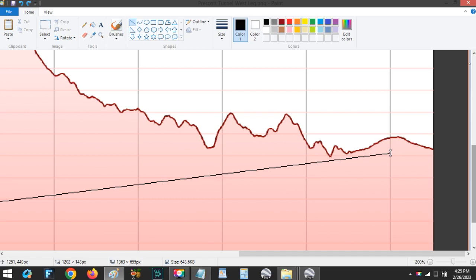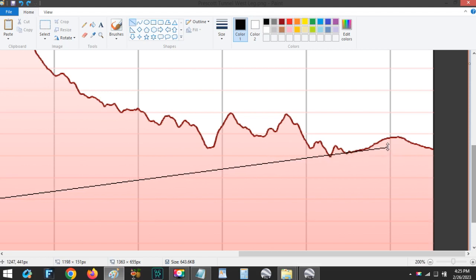Because, oh, on the other hand, low cover is not a problem if you're not underwater or something, so why not make it? Well, it'll be sticking up above the ground, that's why, and that is a wash that is active with water, so it needs to stay at the elevation it's at.